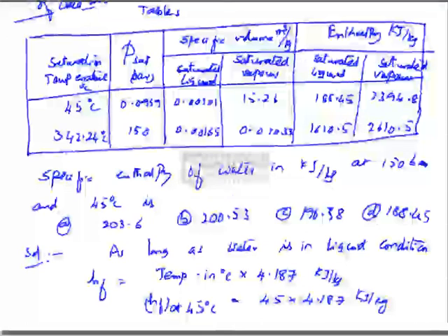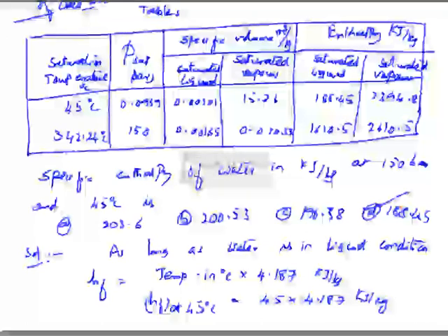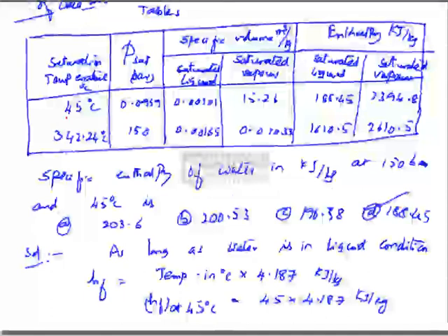The answer should be close to D, that is 188.45. In the table also, the saturated liquid enthalpy corresponding to 45 degrees centigrade saturation temperature is 188.45.